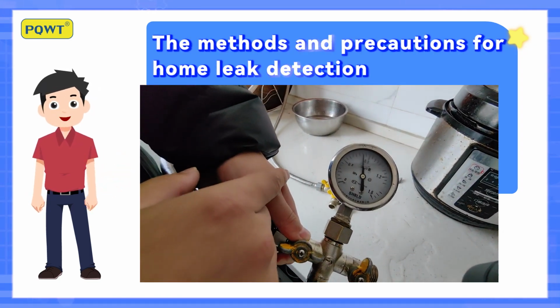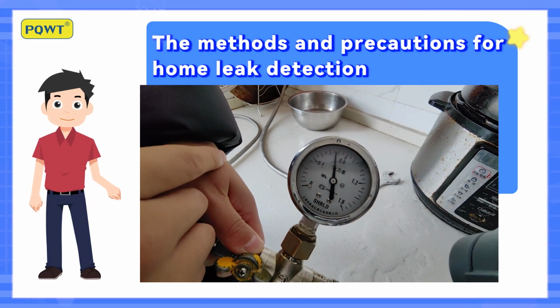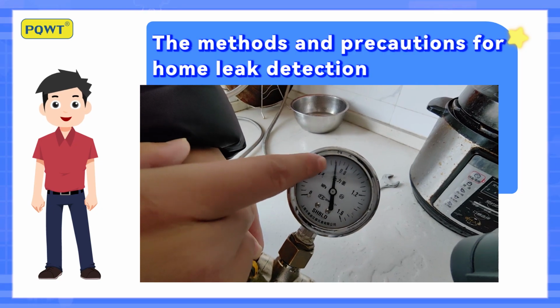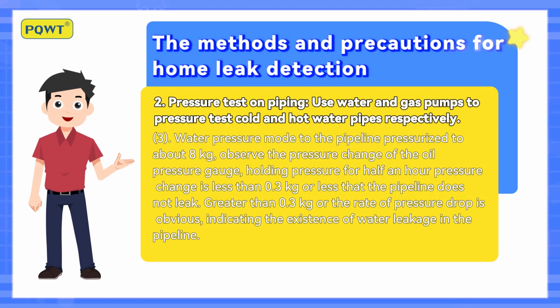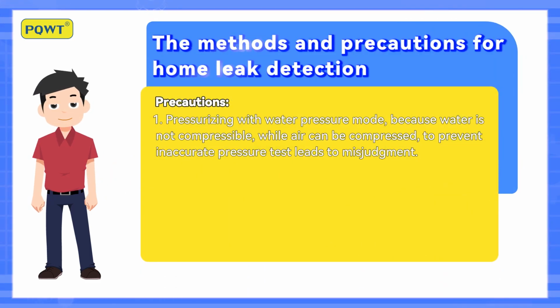3. Use water pressure mode to pressurize the pipeline to about 8 kilograms. Observe the pressure change of the oil pressure gauge. Hold the pressure for half an hour. A pressure change of 0.3 kilograms or less means the pipeline does not leak. Greater than 0.3 kilograms, or an obvious rate of pressure drop, indicates the existence of water leakage in the pipeline.